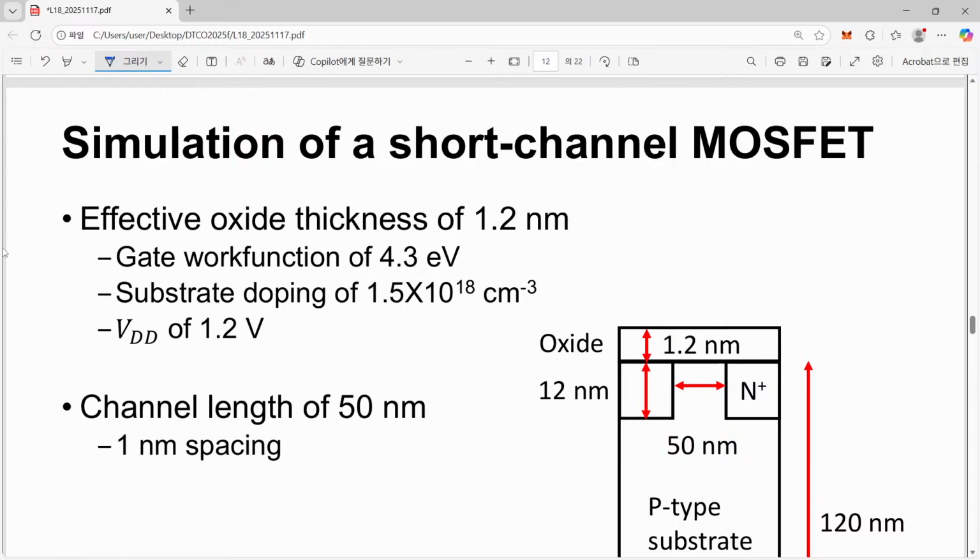No, actually. Nowadays it is almost difficult to see long channel devices, because think about this. You wanted to make a long channel FinFET. If you really wanted to do that, then you have to make your dummy gate longer than the others. But how did you make your dummy gates? You made uniformly spaced polysilicon or amorphous silicon.